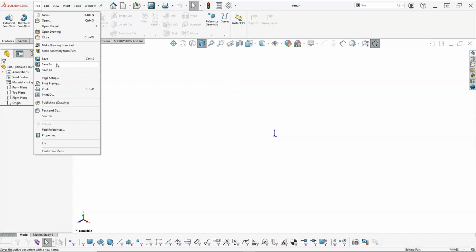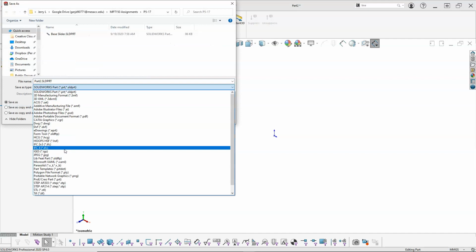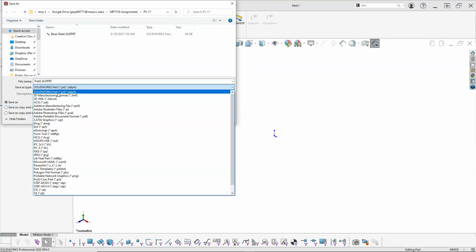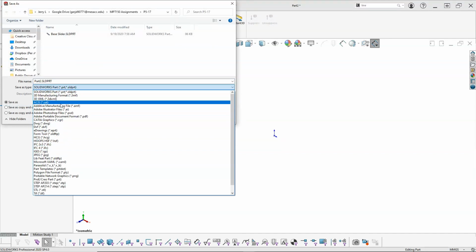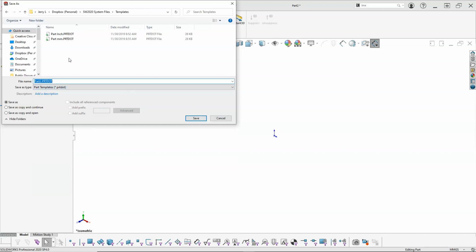And then I'm going to do File, Save As. When I do the Save As, we're going to look for my template, which they changed the location: 3D manufacturing, that's the 3D printing, part templates. It used to be at the very top. I've already got my part millimeter, and at that point I could save it. We'll just name it part metric, something along those lines, something that makes sense to you.